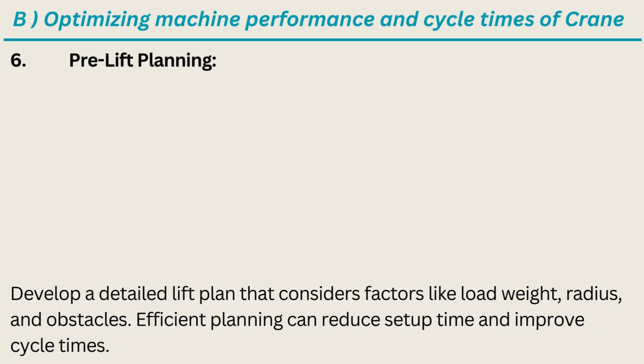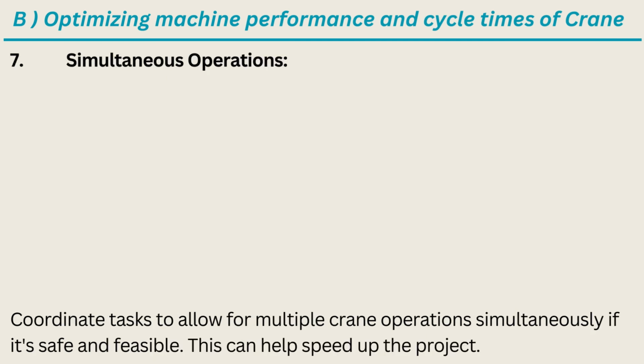Develop a detailed lift plan that considers factors like load weight, radius, and obstacles. Efficient planning can reduce setup time and improve cycle times. 7. Simultaneous operations.